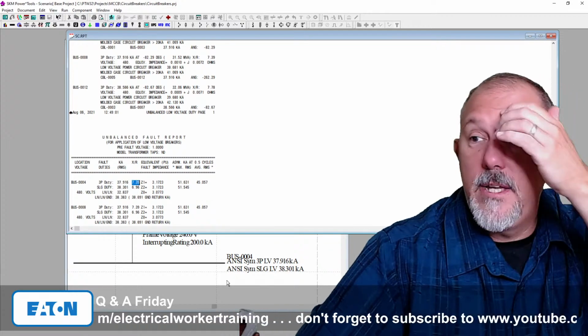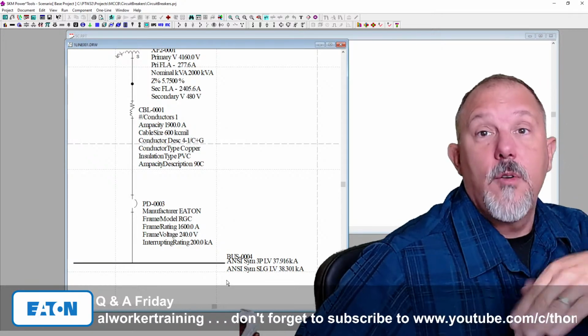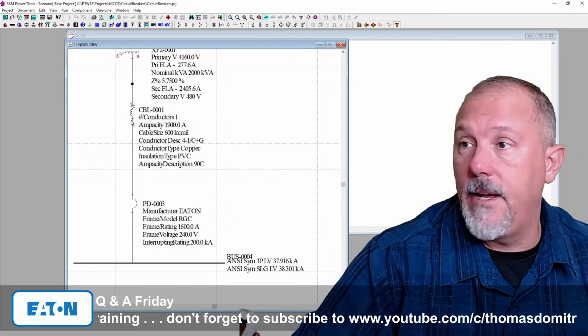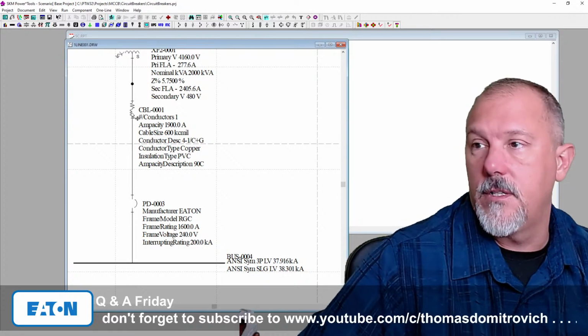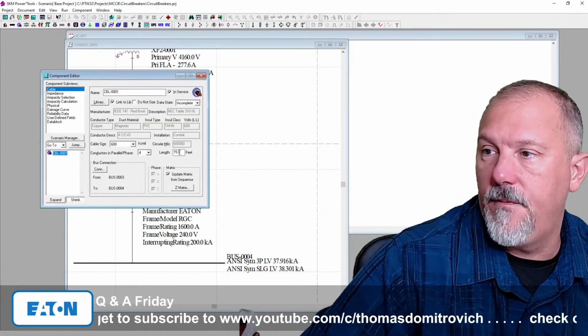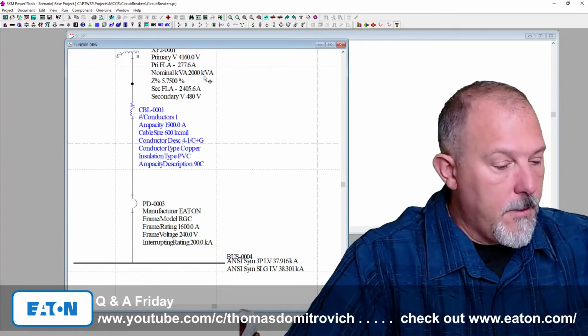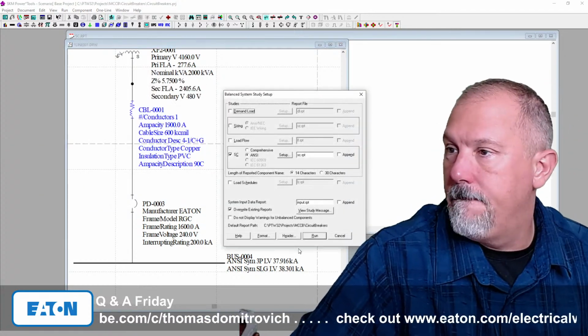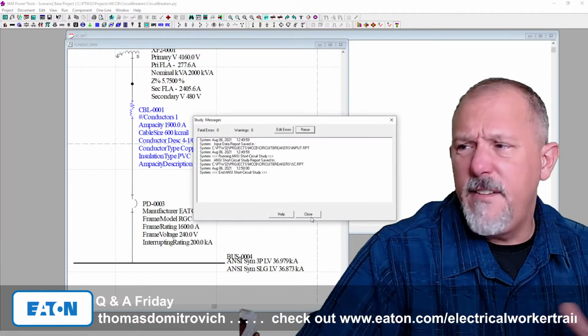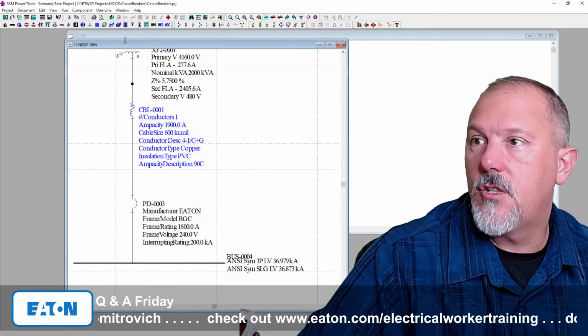Okay, so now let's do this. 7.39 would be greater than the 6.6, right? So that would be a little bit of a cause for concern. Let's take this from 15 to say 30 feet and rerun it. Control A, run, forced run. Let's go back to our report.